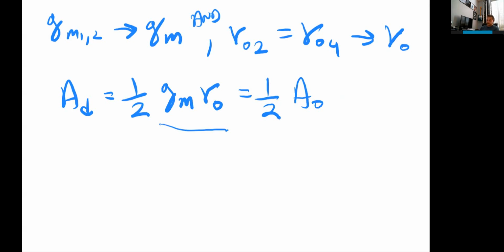So that's what this says. So if I continued processing the signal differentially, then I would have more dynamic range, but that would make my circuit more complex and more expensive. So I can get back some of that gain later with subsequent stages of amplification.